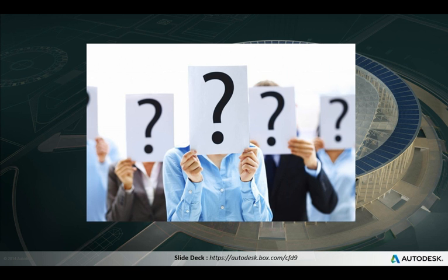Yes, it works fine with slip symmetry, Paul. That's completely okay. If you had a large room with a fire in the middle, then you could theoretically cut it in half. Just realize that it's really not that symmetric. It's very much a transient analysis, but it will work. What I mean by that is that there will probably be some oscillating and biasing flow around the symmetry.